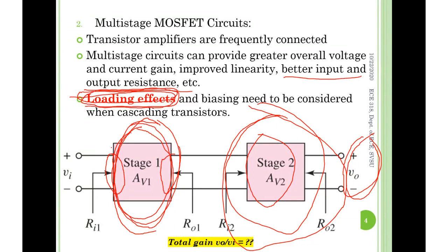We had two multiple choice problems on this in midterm 1, so keep this in your mind. Without taking care of the input and output impedance, your gain is terrible. No matter how big the gain you're designing, it is useless without decent input and output impedance. You see that.